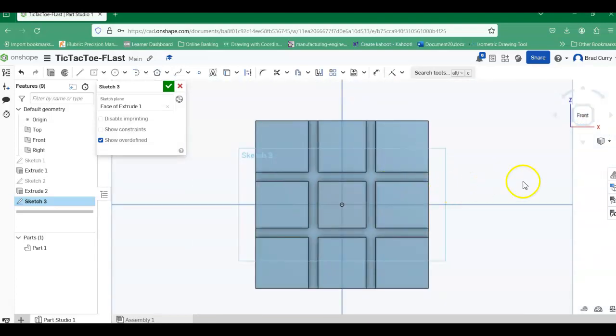Now, I'm also going to create some construction lines here. So I'm going to left click here on the construction line, and this is going to be an actual line now that's construction line. And I'm just going to kind of drop these in here. Notice the difference. Make sure that it is a vertical line. And that locks in. So each time I'll create a construction line, come back.